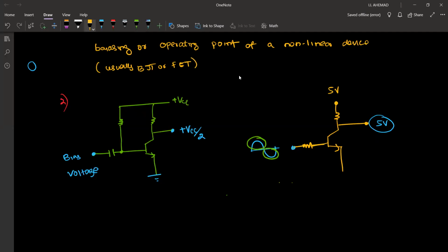Okay, so here, now let's say we have not biased this. If I didn't bias this, then IB current is zero. IC current is also zero. Therefore, there won't be a potential difference. When there is no potential difference, this voltage has to be 5. Is that idea clear? Now I have not biased this, okay? No biasing, so it is at 0 volt.